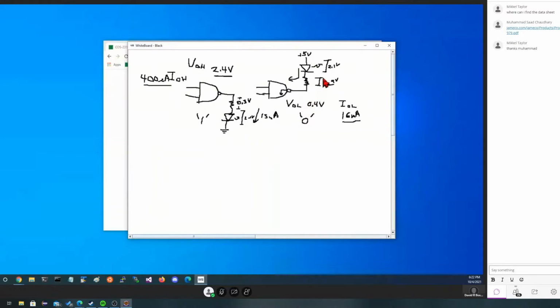We still need to drop 2.1 volts across this, and we still have to because the LED won't light up with less than 15 milliamps. So this is right on the edge. This would not be a design that would be acceptable. We would want it to be closer to 20, just absolutely minimum, and more like we'd want it to be able to have maybe 30 milliamps or something, so we knew we had plenty, which we then could use a resistor to burn up, basically.